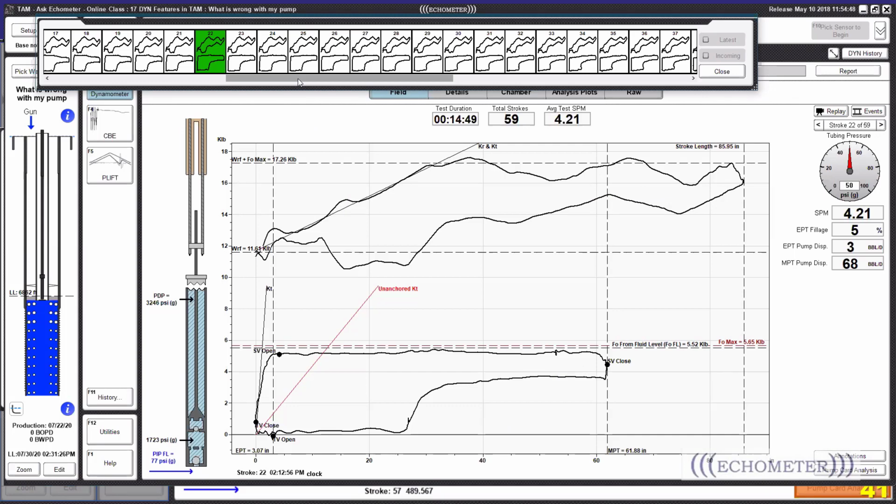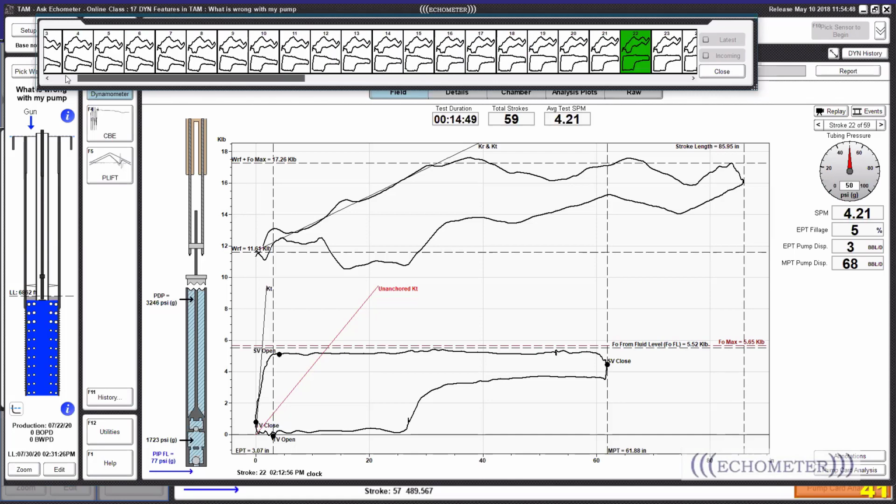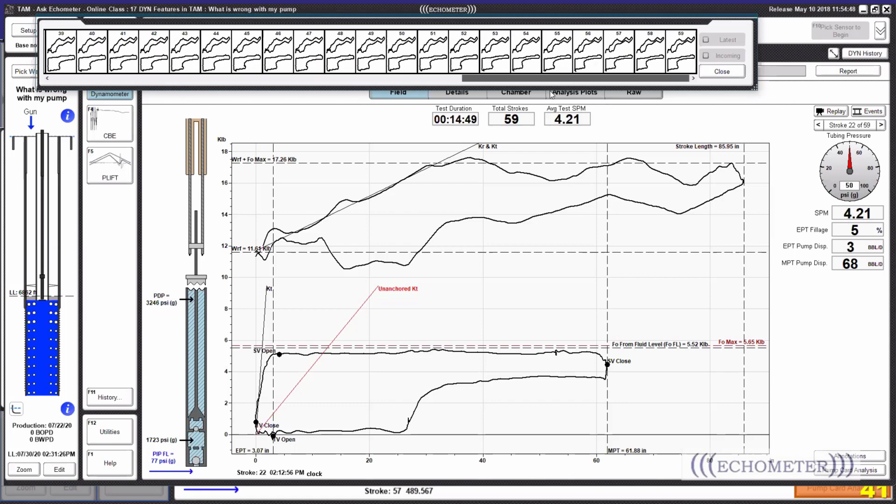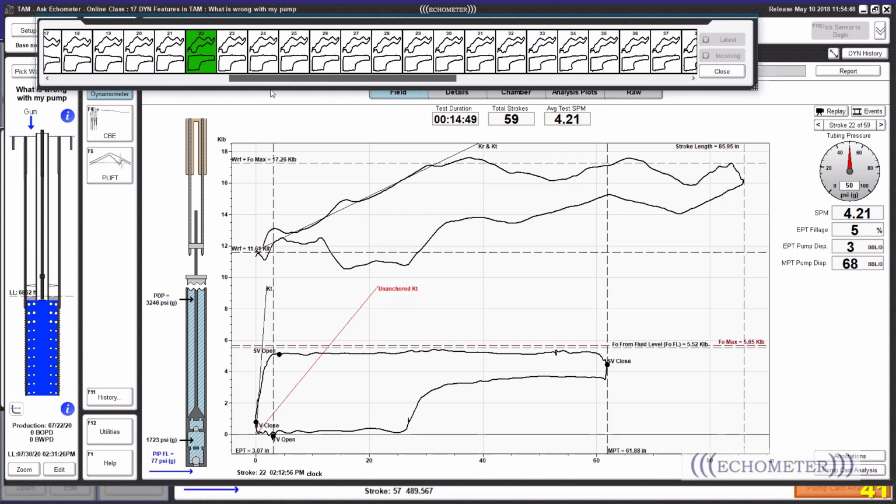So first, it has a surface condition that is not appropriate for the measurements. It has a PRT measuring on a bent polish rod and a rod rotator. And I'm glad that he had the rod rotator because he had the slope tilting down, horizontal tilting up, and this is normal because the bending of the polish rod is changing position. And the cross-sectional area where the PRT is measuring is changing while the polish rod is rotating, and this would be the representative card.